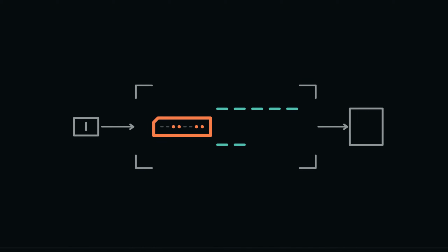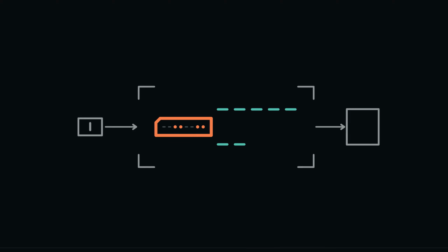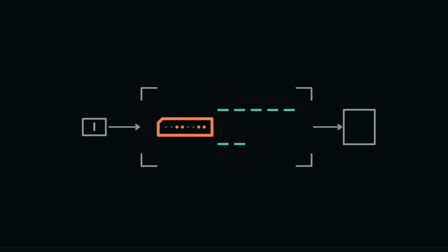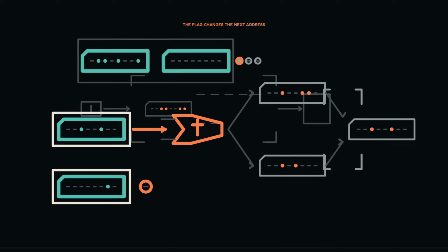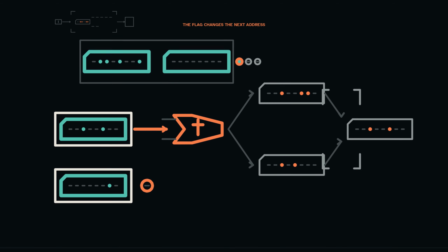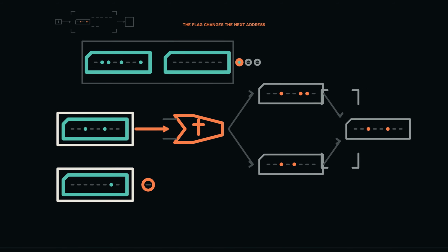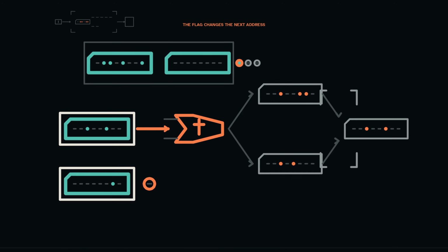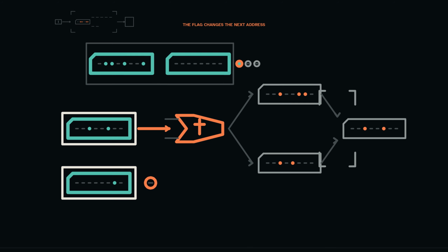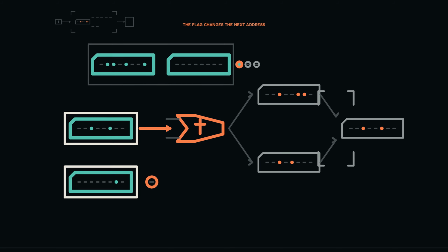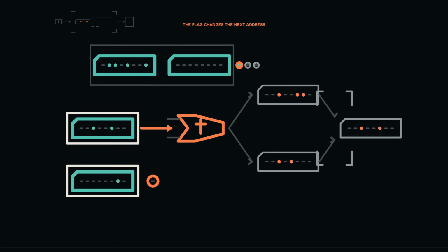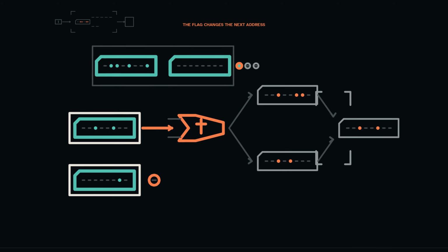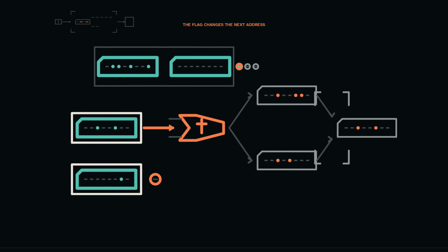The instructions remain in a straight address order. Repetition appears because selected instructions replace PC with an earlier address. The state changes on each visit, so a loop is repeated control flow, not time circling back. The first subtraction has already committed R0 from 3 to 2. The compare instruction at 22 computes 2 minus 0 only for flags. R0 remains 2. The result is non-zero, so 0 is clear, its top bit is clear, no borrow is required, and there is no signed overflow.